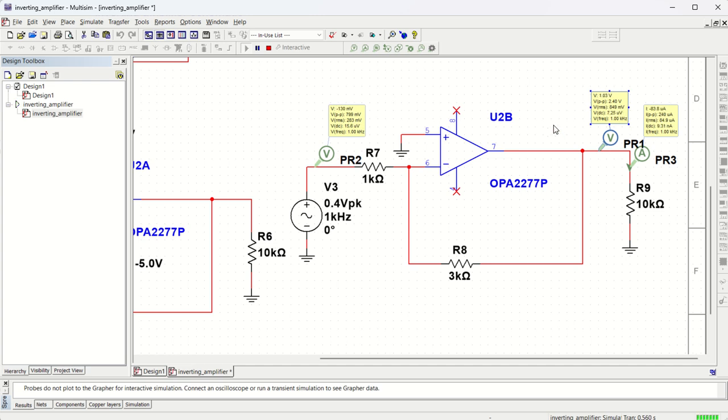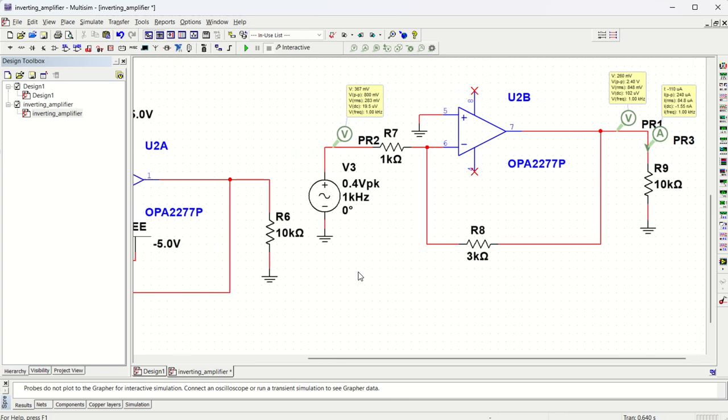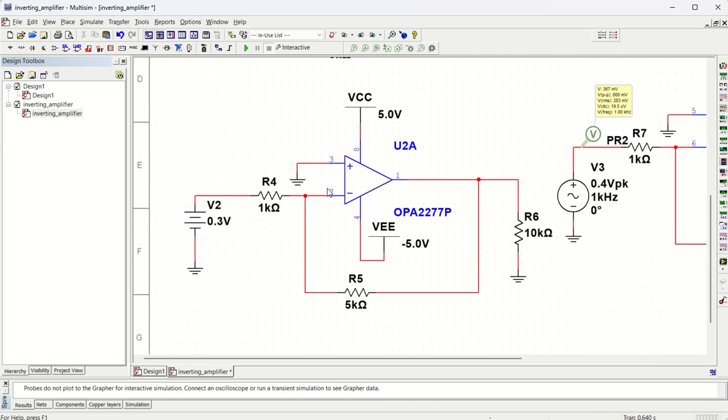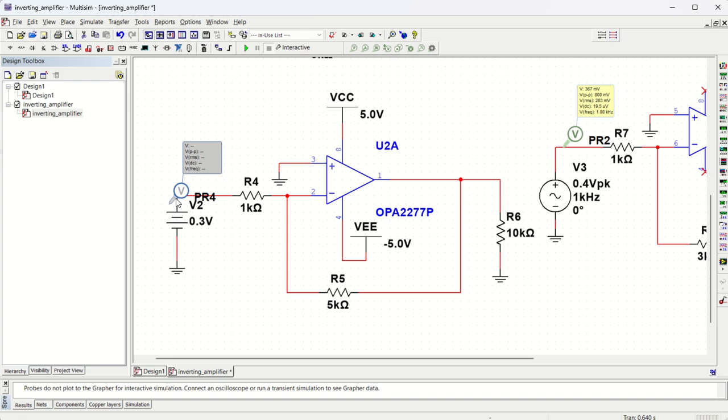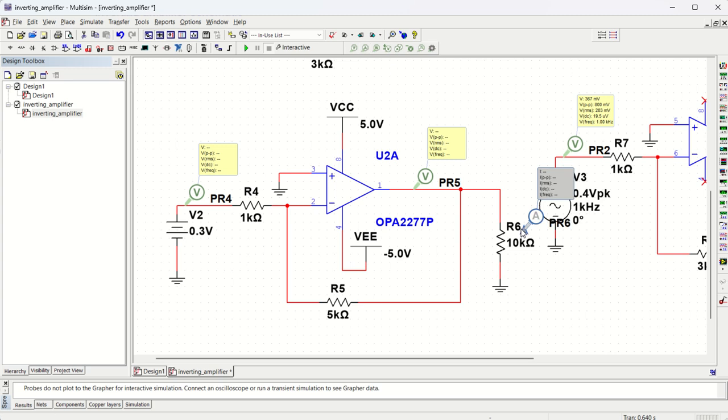Okay. So if you have a DC input voltage, what you can do? Let's say we had here a DC input voltage, right? Yeah, here a DC input voltage. So the current and voltage will be DC signals. So I will quickly put in another probe. Let us say a voltage probe I will put here, and a voltage probe I will put here, and one current probe I will put here. It is going to be on the negative side. Okay, you will see the current is negative.